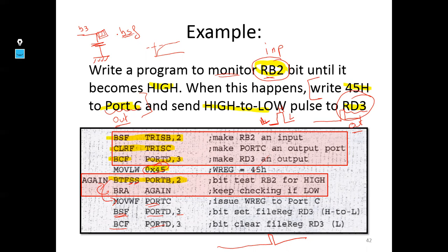So if you read the value just after sending the set, you will read the value 0. Why? Because the capacitor didn't charge. And here time is very short time. So it's not enough for charging the capacitor, especially if you have a high capacity capacitor. So when you read it from the port, you will find the value as 0.